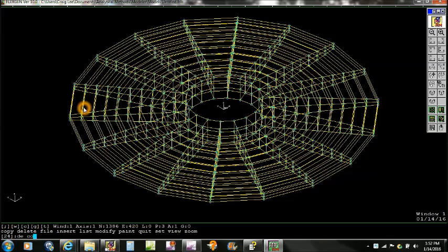So now I want to delete all the coincident nodes. Because I did a copy command, there's a lot of two nodes occupying the same location, and I want to get rid of all those. So I do a delete coincident, and I select all the nodes and the distance between them, and then I'm going to be deleting 792 nodes, and that did that.